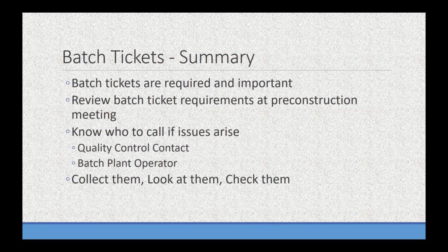So in summary, batch tickets, they're important. They're required per Spec 4. We should be reviewing these batch tickets as they're delivered before the concrete's placed. We should review the batch ticket requirements at the pre-construction meeting. This is a perfect time because the last thing you want to do is have a batch ticket show up that doesn't meet the requirements, and then you're going to be scrambling. Another thing you should check on is know who to call if issues arise. Two main people you probably want to call: quality control contact for the concrete supplier, potentially the batch plant operator.